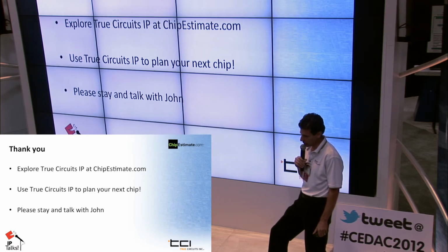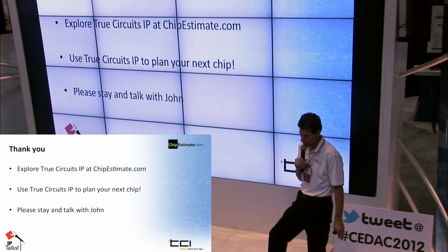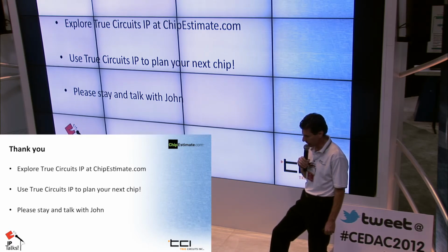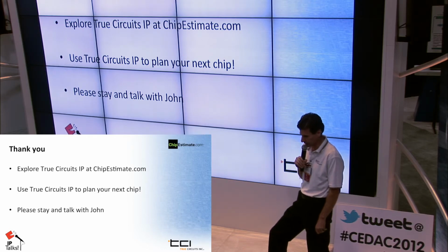For metal stack, we know the designs use the lower levels of metals, so typically in TSMC processes they are not impacted by higher level metal stacks. But for VTs and things, we typically just use standard VTs. If you are using some special combination, we might be able to take advantage of it, and we could discuss that with you.